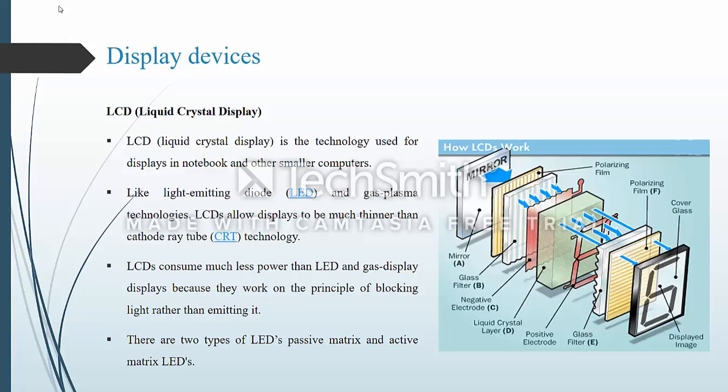On the two pieces of polarized glass, a special polymer that creates microscopic grooves in the surface is rubbed on the side of the glass that does not have the polarizing film on it. The grooves must be in the same direction as the polarizing film. You then add a coating of nematic liquid crystals to one of the filters.